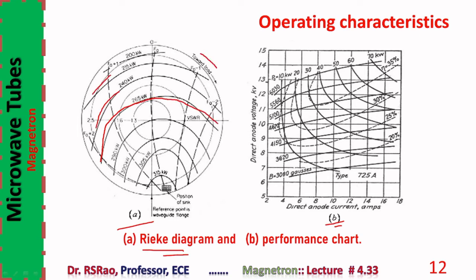Load is shown as VSWR over a horizontal axis: 1.3, 1.6, 2.5, etc. One can also see somewhat vertical, broken long lines with indications F0, F0 minus 1, F0 plus 1, etc. This F0 refers to frequency. If we move towards the right side, it is a reduction in frequency; on the left side, it is an increase in frequency. So these are contours of constant frequency.